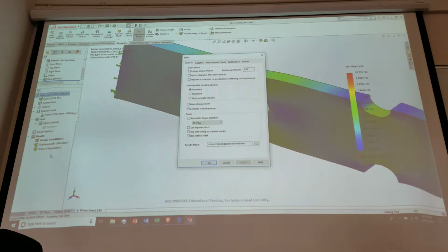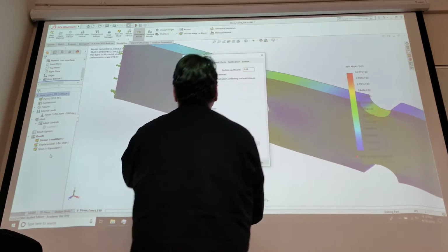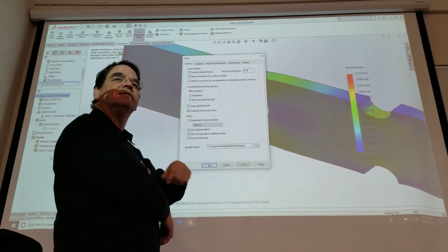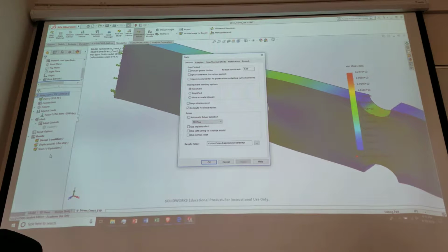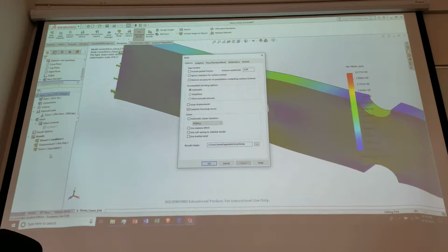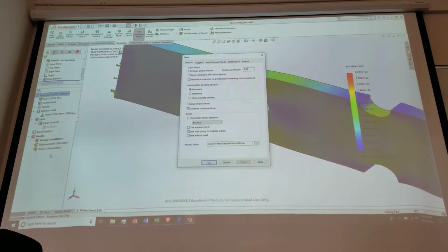Okay, down here we have large displacement. This is a large displacement flag. If the problem starts exhibiting large displacements, and sometimes yours may, and in fact, sometime during this class period, you'll get a warning: large displacement. Should I run with the large displacement option? That almost always means you screwed up your boundary conditions.